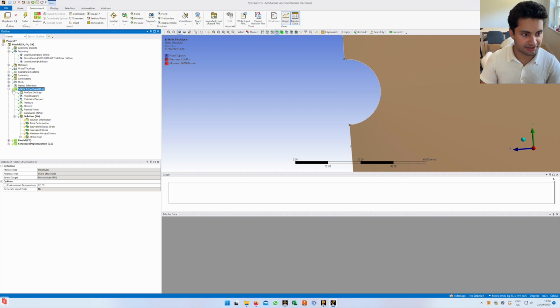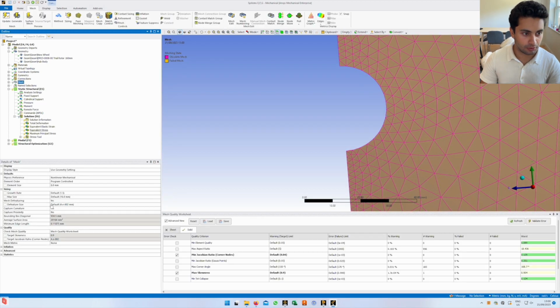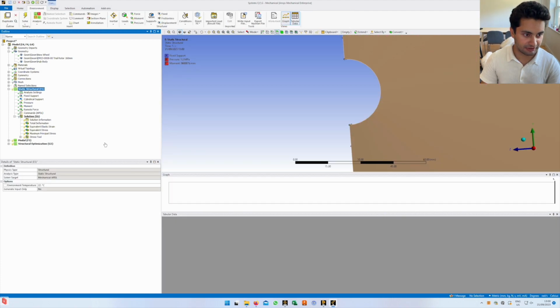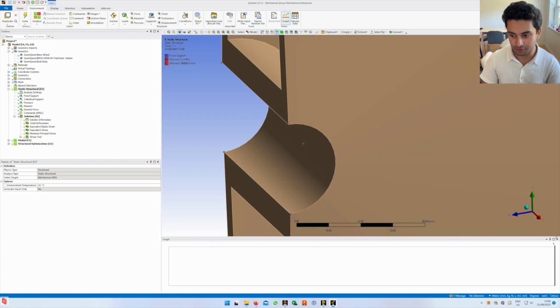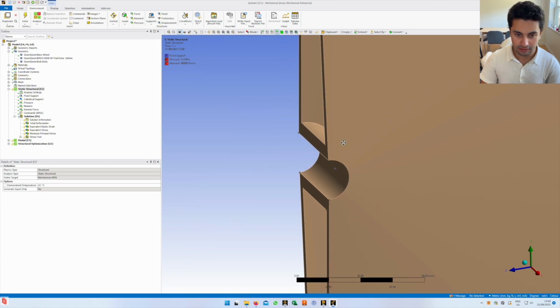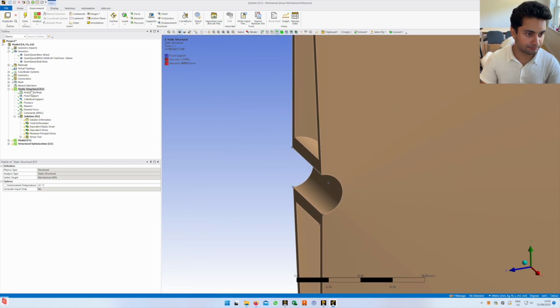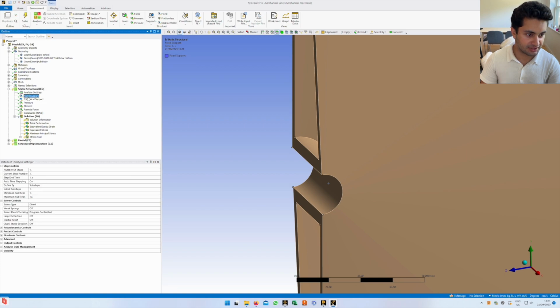Okay, and next, you'll have generated the mesh, and then you're ready. Once you've gone through the mesh quality worksheet and everything looks fine, we'll go down to static structural, and here is where we have to define all of our loads and supports. So first thing we'll do is...